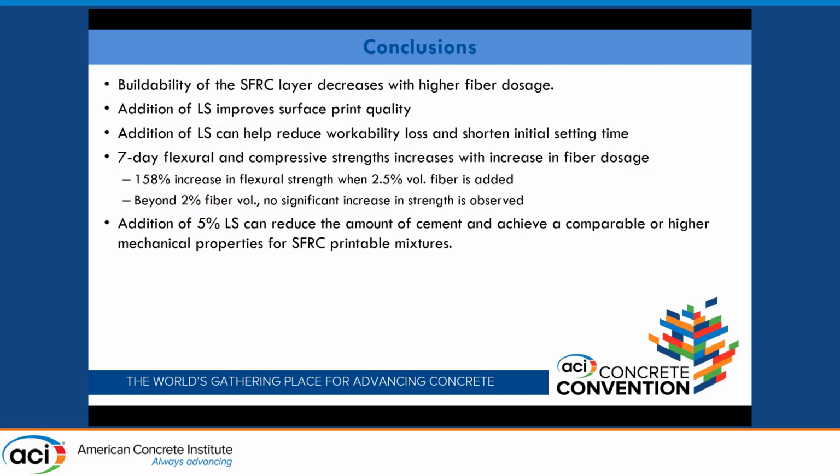For our research, we were able to print up to about 2.5% volume, which is actually a lot of steel fiber in the mixture. And overall, incorporating limestone powder into the cement matrix can help you achieve comparable or higher mechanical properties for this steel fiber reinforced concrete.